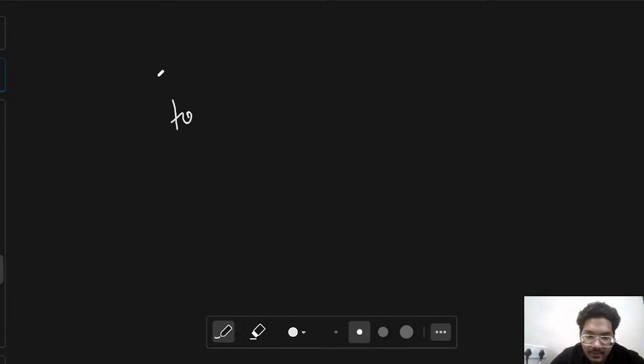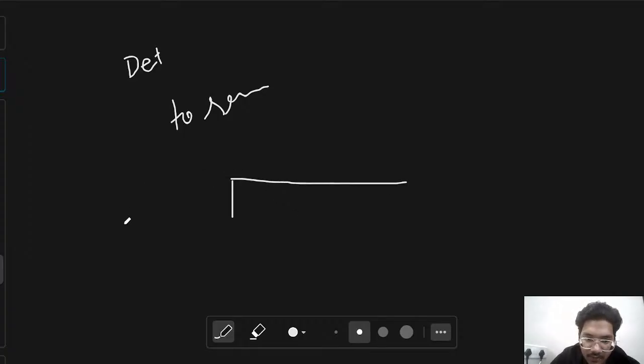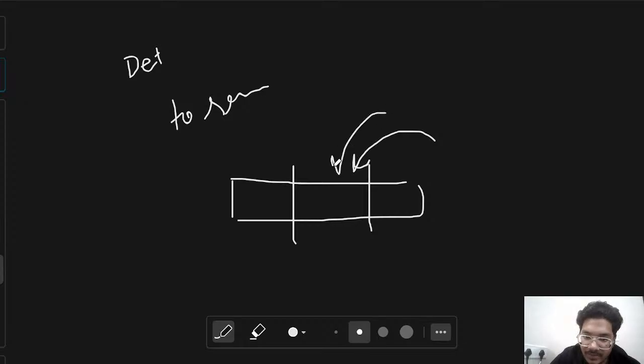As we know, the best optical detector has high sensitivity. To increase the sensitivity, the depletion region should be longer to absorb more photons. So how do we increase the sensitivity? We have to increase the depletion region, which absorbs more photons.